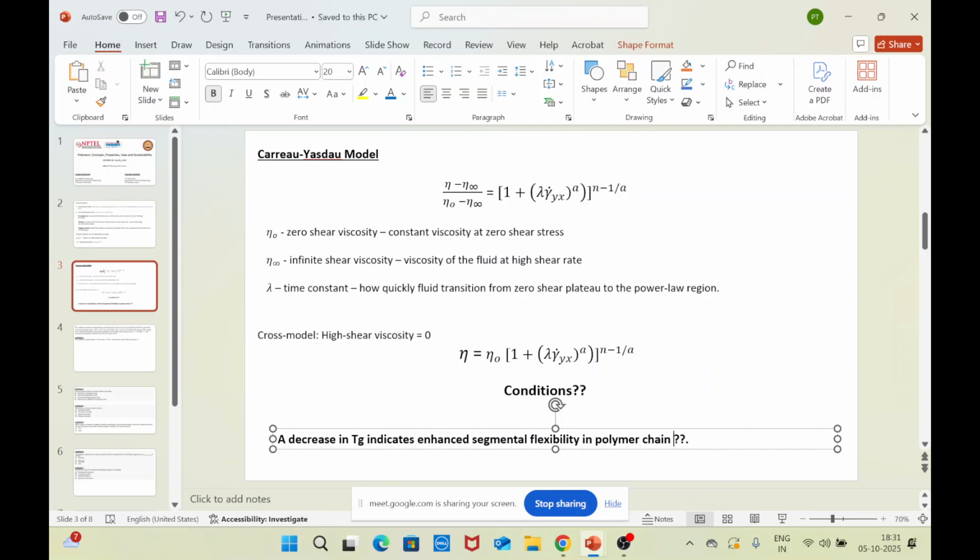So these two phenomena of plasticization and solubilization happen in the case of branched or linear polymers. However, when you go for cross-linked polymers, called thermosets and rubbers, they have cross-links in them. Those crosslinks are typically covalent in nature. They are covalently bonded to one another. So even if you put these polymers in an excess of solvent, they are not going to break down or separate, unlike linear or branched polymers. So that is where the concept of swelling comes in.